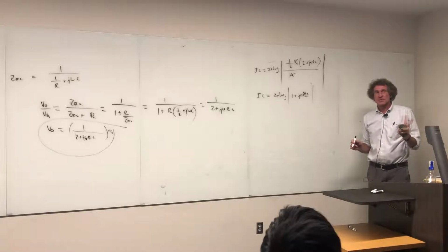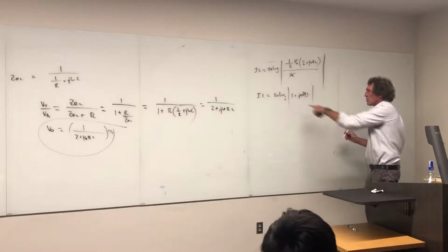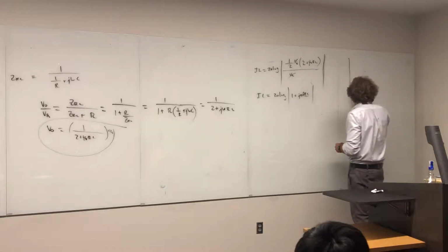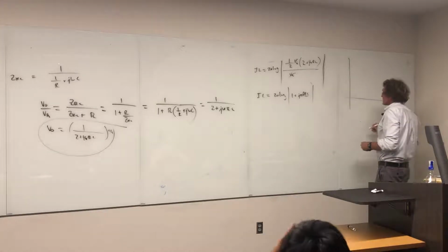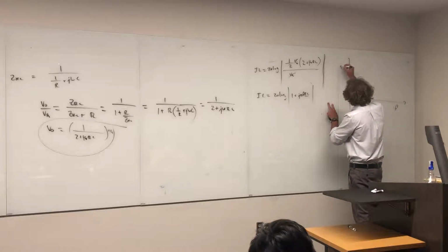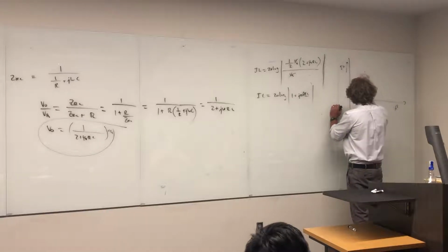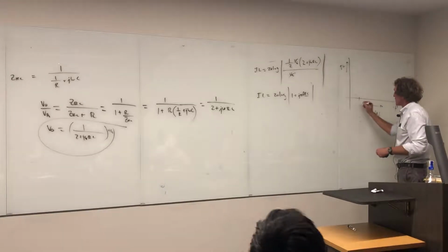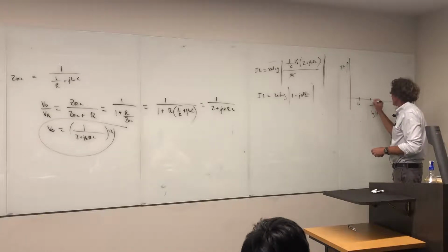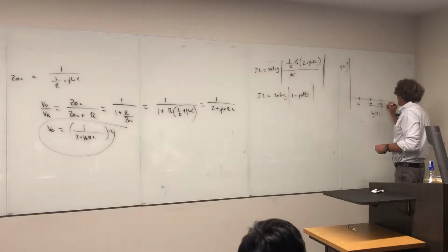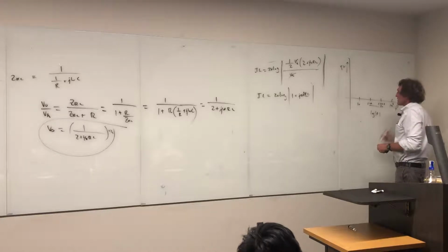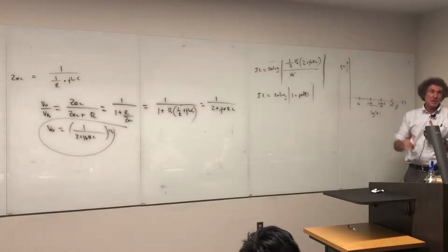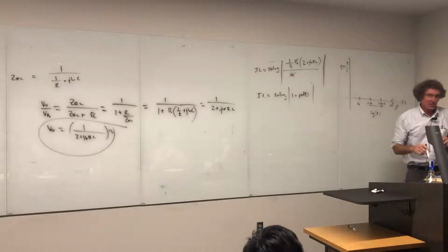All the time these constants start wavering. Now, if I'm plotting that versus frequency, I'm going to do it here. Typically the way we do it, we put insertion loss on this axis, and this axis is really going to be the log of f, but you're going to have the paper take the log. So if this is 10, this would be 100, this would be 1,000, and so forth, 10 to the fourth. The paper takes the log. In other words, it's a log paper, but it's linear on the vertical axis. On the vertical axis, it's 20 times the log of that.